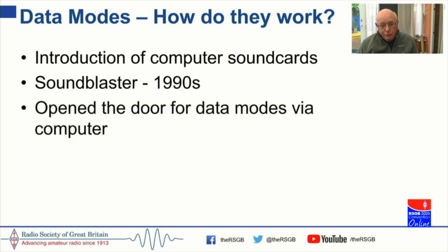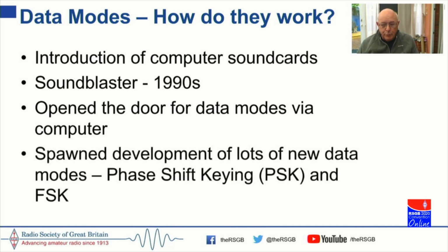And of course, once you've got a sound card in the computer, that completely opens the door for data modes via computer, and that spawned the development of lots of new data modes, phase shift keying as well as frequency shift keying. So you can do those as well. It's not restricted to frequency shift keying. Anything that you can emulate in audio, you can send through an SSB transmitter and use it. So that really makes the generation and reception of data modes quite straightforward.